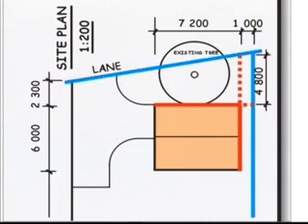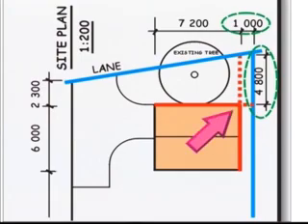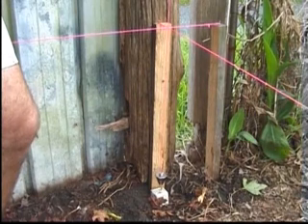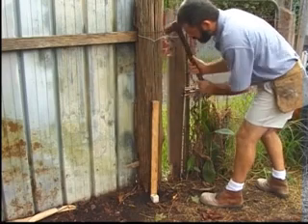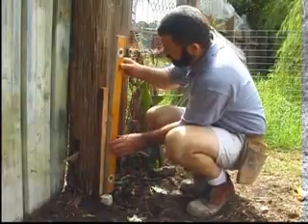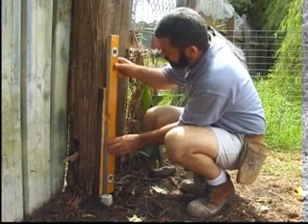The side boundary is established as a datum or starting point by running a string line directly above the two survey marks at the corners of the block. This boundary string line is fastened to pegs driven into the ground behind the survey marks. The string is plumbed to the marks to make sure it lies vertically above them.